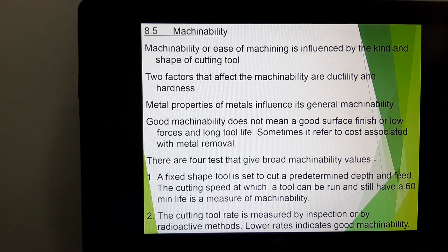Alright, students, welcome back to the continuation of our lecture on Unit 5, Machinability. So we were talking about metal cutting. We spoke about the different angles: side cutting edge angle, back rake angle, positive back rake angle, negative back rake angle, side relief angle. Like I told you, every cutting tool, whether it's a lathe cutting tool or a milling machine cutting tool, comes with a tool geometry, meaning that it is associated with certain angles, and all these angles contribute to a good cutting.